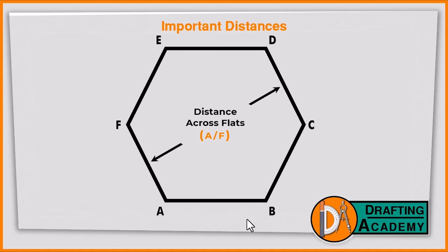Now, what guides us to know that all these three distances are distances across flats? The binding principle in getting your distance across flats is that you should always get the perpendicular distance between sides of a polygon that are opposite each other. The key to knowing that two sides are opposite each other is checking if those two sides you picked are parallel to each other.